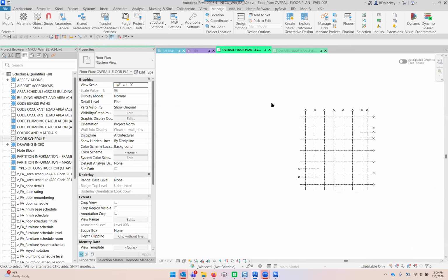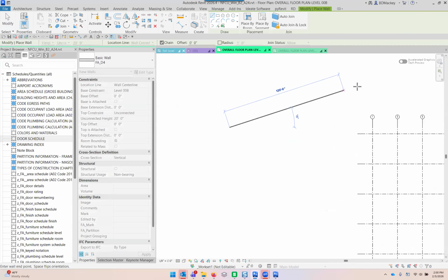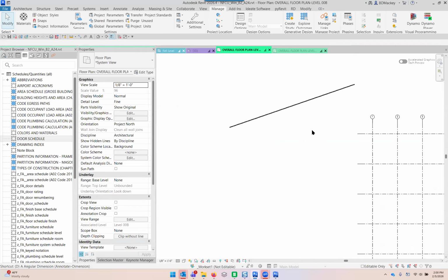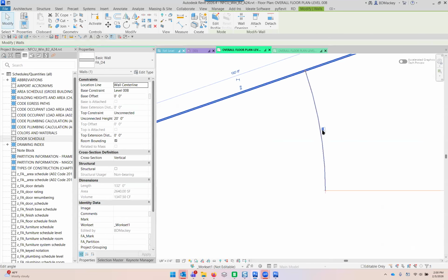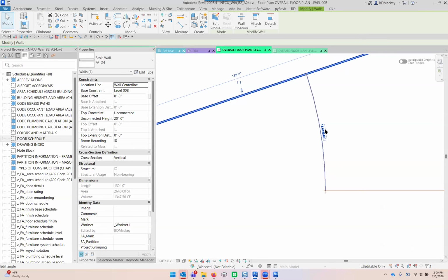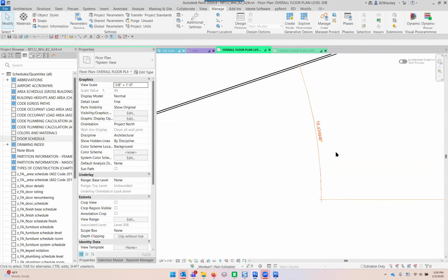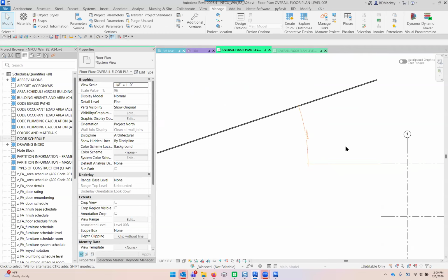And you don't even always have to use those just within a family environment. If I were to come in here and draw something in the project, and I really wanted this angle to be a 4/12 pitch, if I go put an angular dimension on here, you can do that within families, within inputs. So I can say I wanted that to equal the arctangent of the rise over the run. So this is also a statement, but I'm just doing it where I'm entering a value, and that's an 18.43-whatever degree angle.